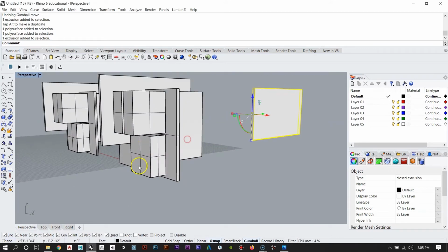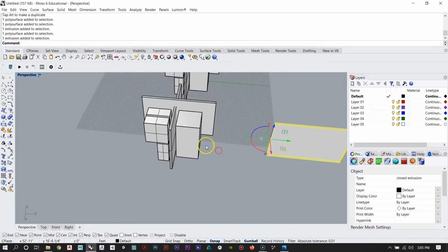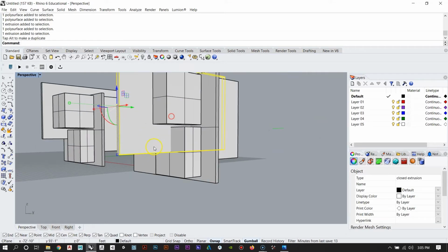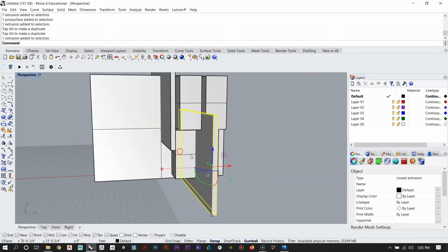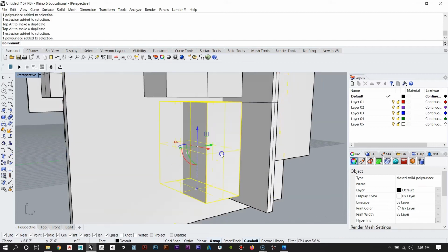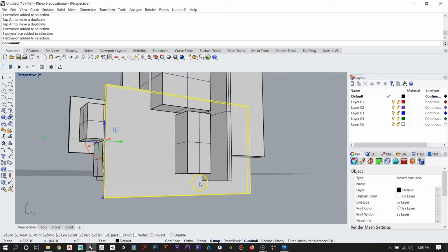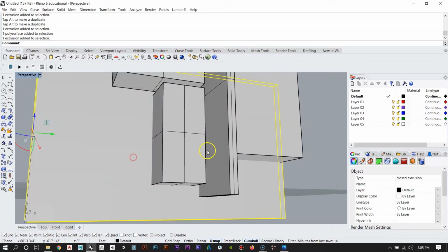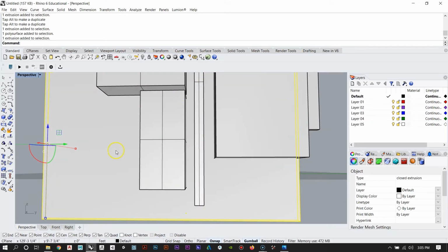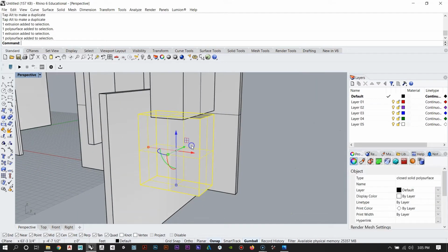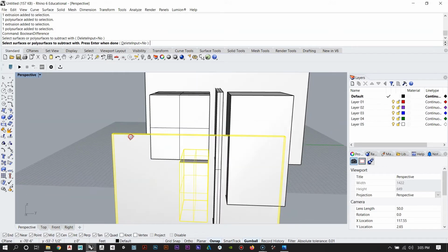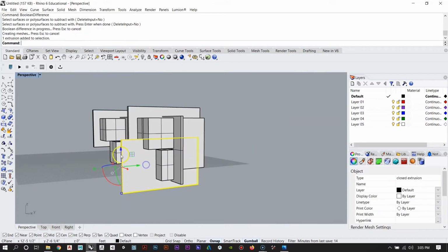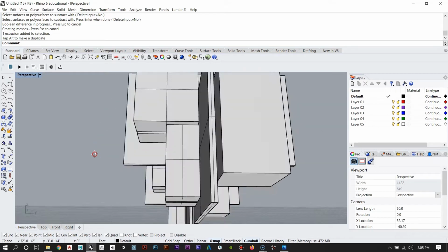So what we'll do next is cut the bottom cube in half. I'm going to take this plane and slide it over and then slide it down. Again, I'm going to make sure that this plane or this wall intersects this cube completely, so it sticks out on all four sides of that cube. So it sticks out over here, up at the top, bottom, and on the left-hand side. So I'll select that, type my Boolean difference, hit enter, select this object, hit enter, and it's going to again cut that object in half for me.